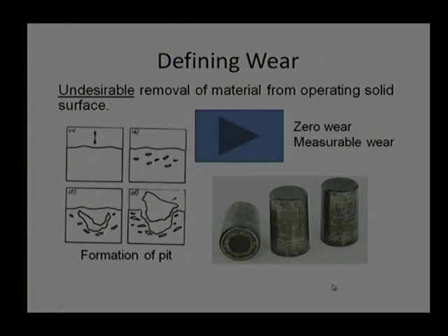Let us see this roller surface. These are roller surfaces. We are able to find there are some scratches, some deformation of surface, or we can say it is losing some dimension, some tolerances. Quite possible that this scar may be 20 to 50 micron, and a 20 to 50 micron change in the dimension of tribopairs means a lot. It is going to change the performance from one domain to another domain, or we can say from full film lubrication to mixed lubrication to boundary lubrication, with a huge variation of coefficient of friction.